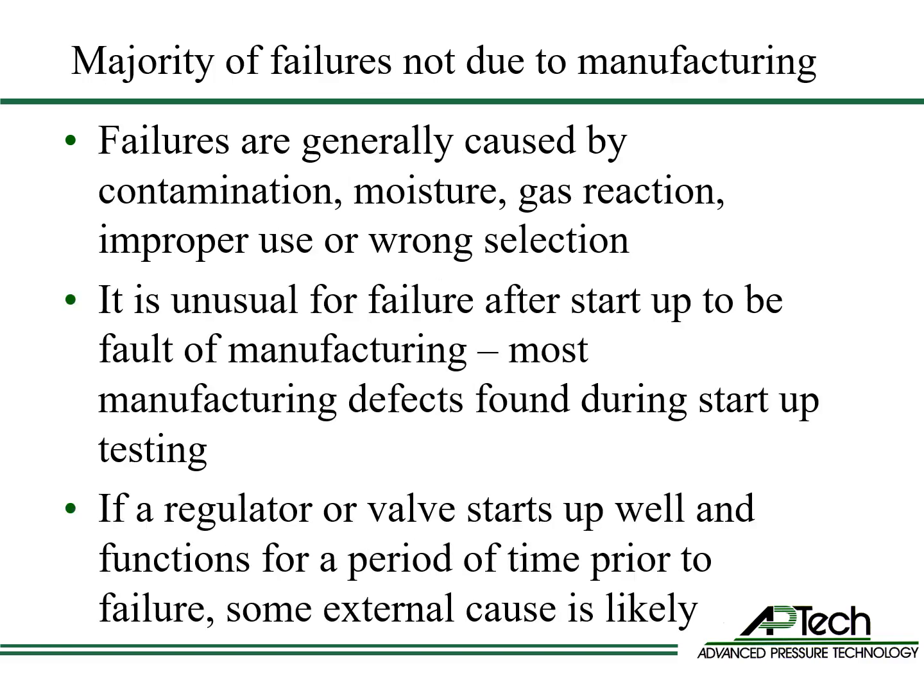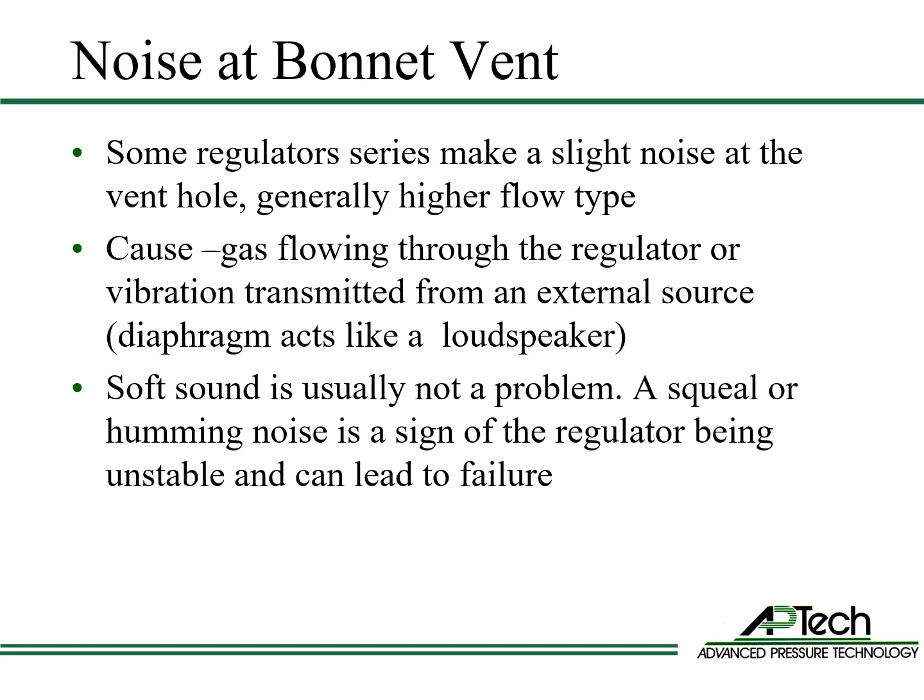The majority of regulator and valve failures are not due to manufacturing defects. Failures are generally caused by contamination, moisture, gas reaction, and improper use or wrong selection. It is unusual for a failure after startup to be the fault of the manufacturing. Defects are often found during startup and testing. If a regulator or valve operates normally during startup and functions for a period of time prior to failure, some external cause is likely. There are some common regulator occurrences that may cause concern, but are normal.